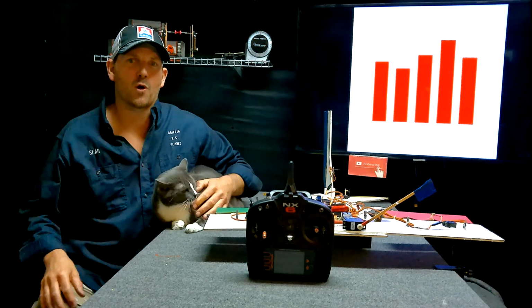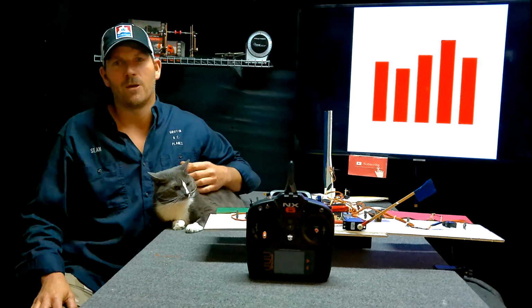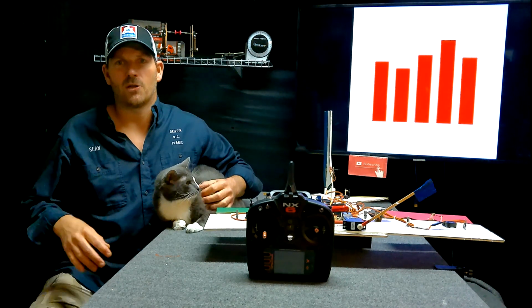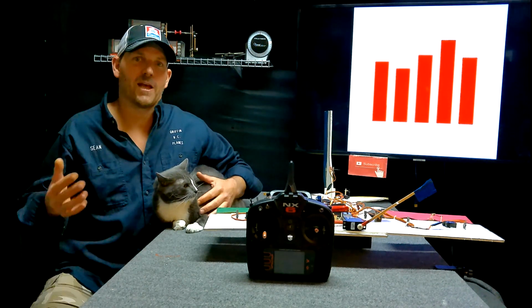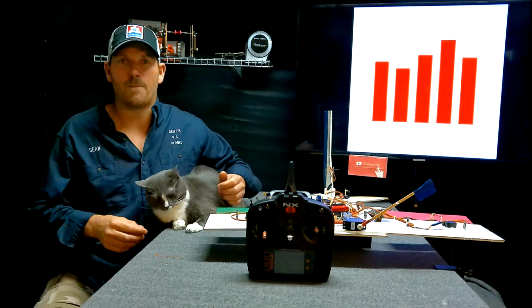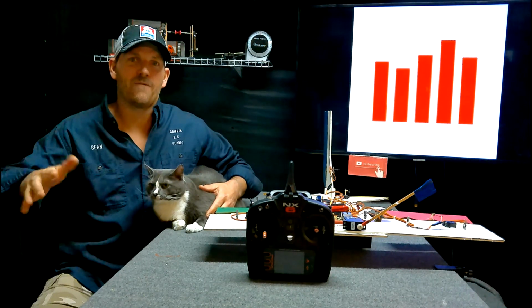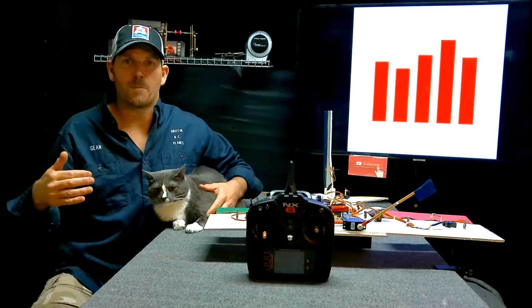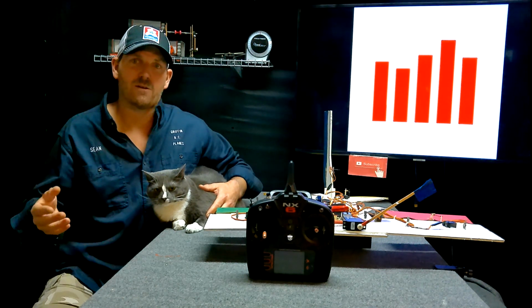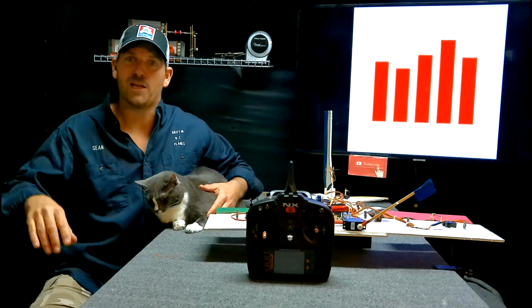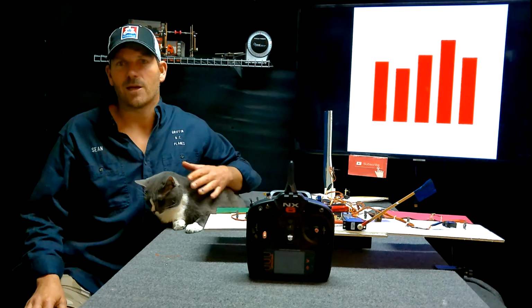Okay, forward programming, part 2, coming up now. We're going to pick out a flight mode channel so that when we flip our switch, we can have different flight modes. One of our flight modes is going to be for AS3X only. That is stability for the wind. Then when we flip our switch, it will go into our second flight mode, and we're going to have full SAFE Select, which is leveling, and the AS3X.